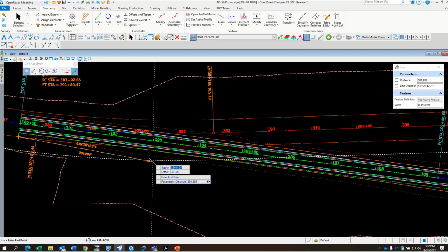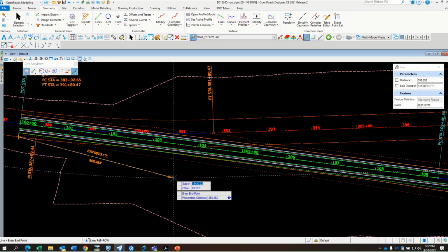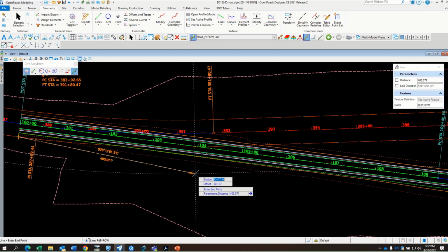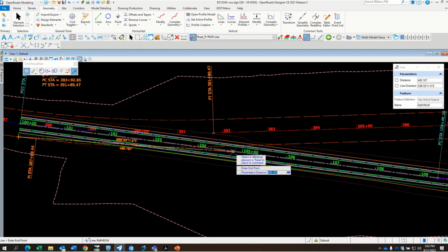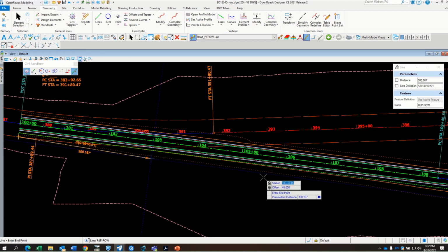And then the next is going to be station 103, right? But look at the station. It's like station 13, which is really just starting at 0, I think. Yeah, maybe. But in any case, each time I think I need to hit that O for origin. I select the proposed right-of-way. It switches to the proper stationing. Remember, I use the tabs to go to 103. Enter, and then we said that offset is 40,